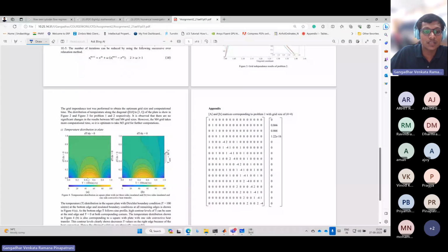You see the maximum is 100 degrees Celsius here, and the minimum is 0 here, as it is a sine function. It starts at 0, goes up high, and comes back to 0 again. So my temperature distribution is 0 at both ends and very high temperature in the middle. This is how the temperature distribution looks. Over the entire plate the temperature is around 60 degrees Celsius, because it is occupied with a light green color, and the color bar indicates 60 degrees Celsius.